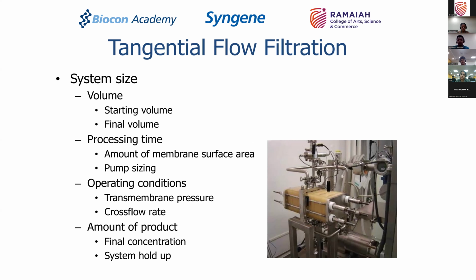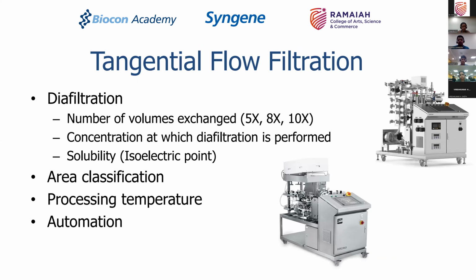that you will get out, and the system hold up which is there, because this again will have liquid in it. Will you use a buffer to drive out the product of interest, for example, or will you do a certain amount of water addition to drive the product and obtain your concentrated mass, which is sticking onto the membranes? These are all important aspects to be considered during tangential flow filtration. Whether you will do buffer exchange, etc.